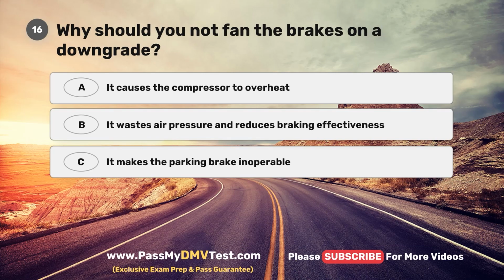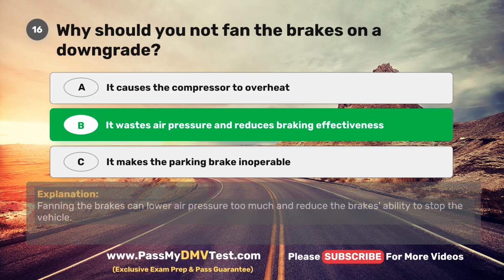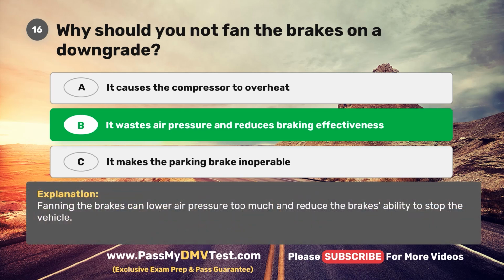Question 16. Why should you not fan the brakes on a downgrade? A. It causes the compressor to overheat. B. It wastes air pressure and reduces braking effectiveness. C. It makes the parking brake inoperable. The correct answer is B. It wastes air pressure and reduces braking effectiveness. Fanning the brakes can lower air pressure too much and reduce the brake's ability to stop the vehicle.